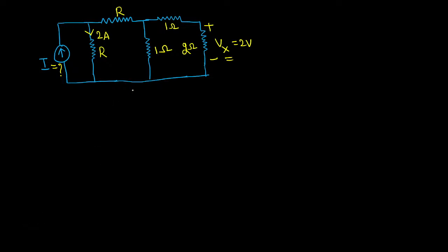Okay, what my mind is thinking is, immediately I am looking at KCL. My mind says that if I apply KCL, the answer will come. I don't want to know any other values. Because see, this resistor value is not given, this resistor value is not given. I cannot play with these now. But what I can do is, they have given the clue. Always try to travel along with the clue. They clearly gave it. This is 2 volts.